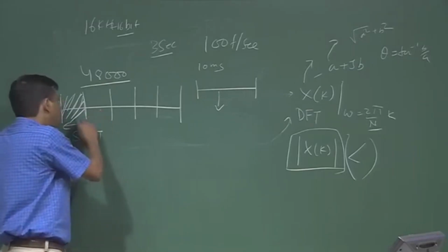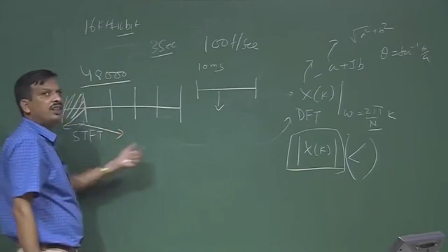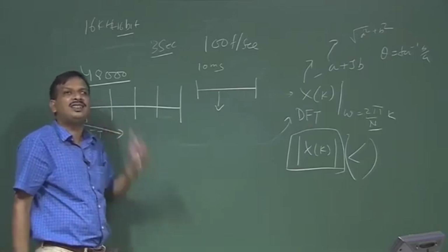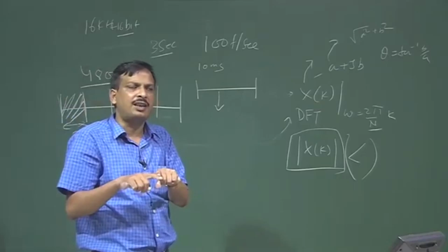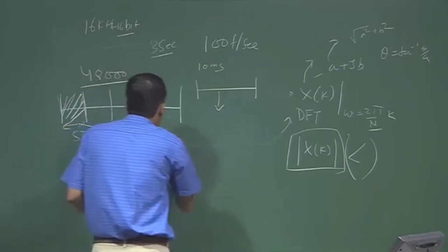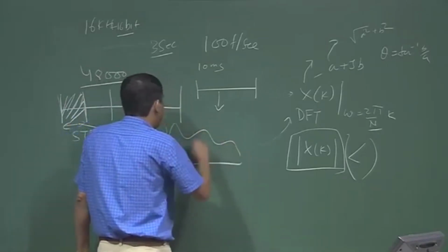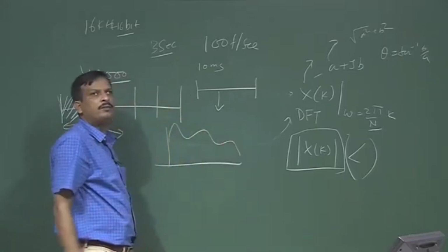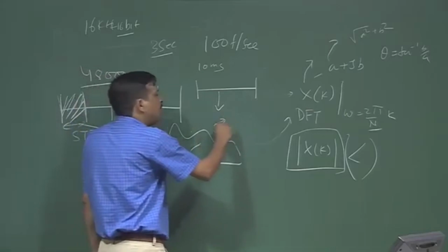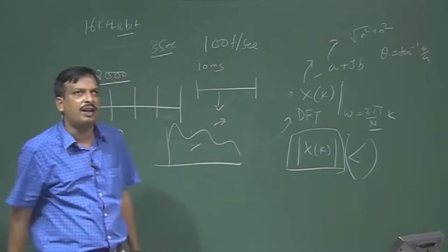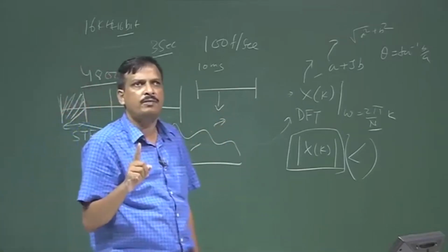So, analysis is when I am doing the transform. Synthesis, when I get back the signal again, is called synthesis. After analysis, after finding that the magnitude spectra is like this, I can modify the magnitude spectra. Once I modify it and again take the inverse transform, I should get the signal back with the modified property.